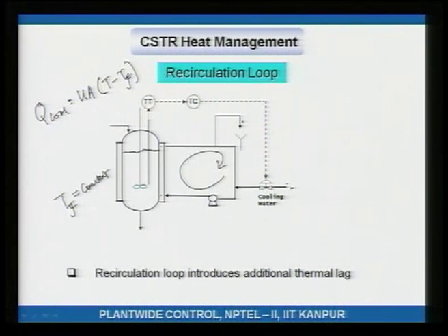Okay. So now if you add more cold cooling water, that means if you open the cooling water valve, since more cold water is coming in, Tj will go down. Okay. So if I call this F cooling water, if F cooling water goes up, Tj goes down. If Tj goes down, Q cool, the amount of heat removed, goes up. Alright.